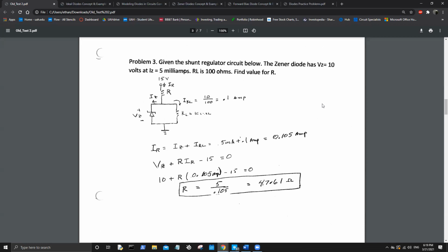So you're saying whatever is going over the resistor is what's going through the diode, if the diode voltage is given. Yeah, in this system, I can definitely see that because they're in parallel, right? Makes sense. And here they just did a current sum, found something, and then used that to calculate R, and they're done.